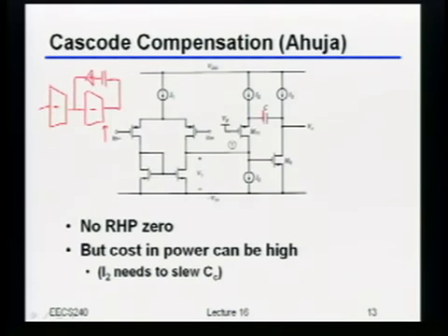So again, the way to see that is just imagine we have the following situation. So imagine that the differential input is such that I push this thing really, really hard in the direction of the two arrows that I just said. So in minus is very large and in plus is very small. Okay? So that essentially all of this bias current is going to flow through there.